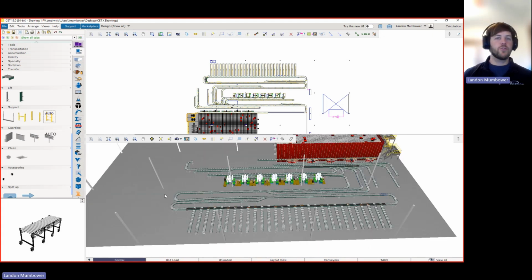So if you have a larger drawing, it's typically good to freeze those sections so that you don't see them. They're not in the way. It helps improve that focus. And you can keep your load size smaller. All right, we'll take questions in the live session.